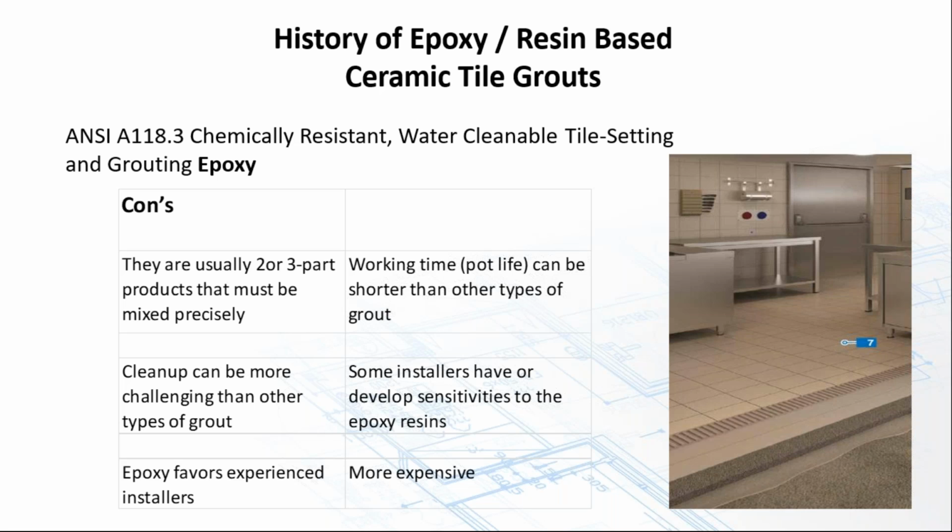We could set up an epoxy that would set up quicker, but there's a good chance that you might not get it out of the bucket, you'd be throwing most of it away. So we are limited in how quick an epoxy can set up and being able to work with it. And it's a matter, if you're doing a repair, of properly covering it so it can cure out properly before you put the application back into use.